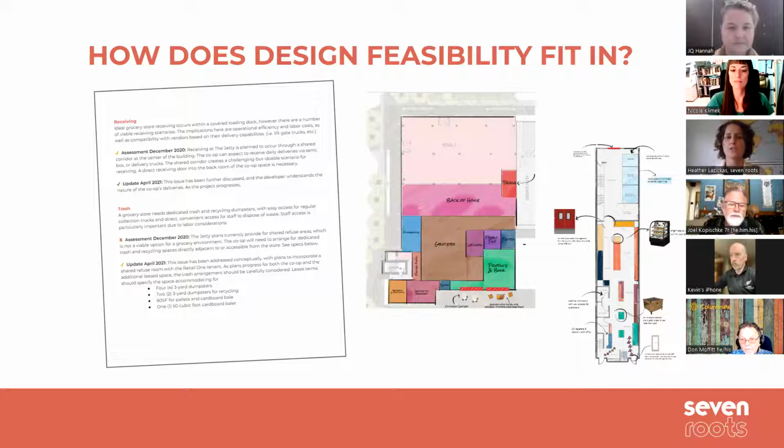Our approach is to assess the site for challenges and opportunities before locking it in, so that when you go into lease negotiations, you know what you need to succeed. For example, you need to know: we're going to receive on this side and might need a variance, or we need a new curb cut, or we need the landlord to provide X, Y, or Z.